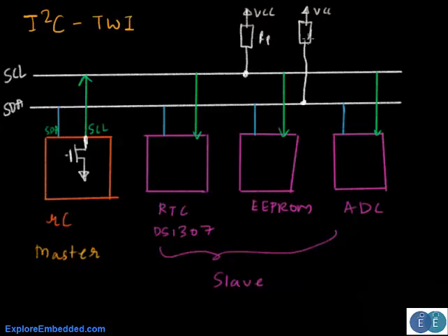You could understand why we require a pull-up, because if it is not grounded, the pin is floating and we do not have a stable voltage on the line. Also remember that when the bus is not operating, both the lines are pulled high, and that is where we would start the discussion on communication. Since there are only two lines on which the communication needs to happen, specific timings or specific combinations of these two signals are generated in order to transfer data between devices.